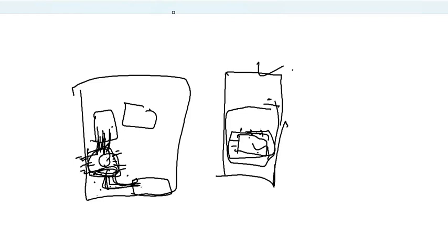One thing to keep in mind here, always try to do a floor plan in such a way that the signal flows seamlessly. It should not go back, come back, take zigzag turns when you're doing a floor plan. Keep that in mind when you are doing an initial floor plan of your module.